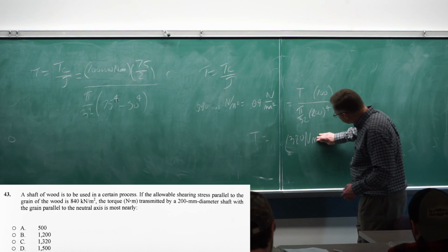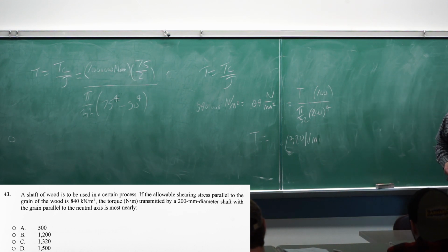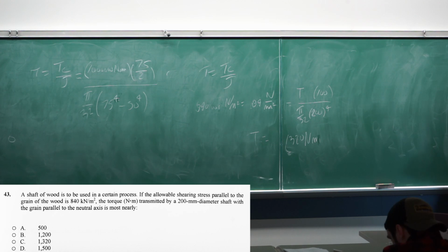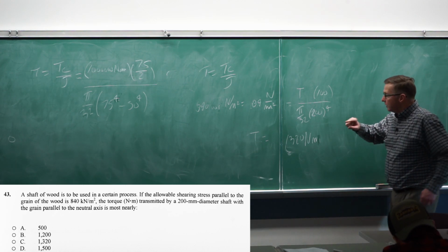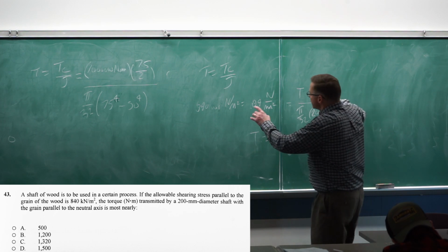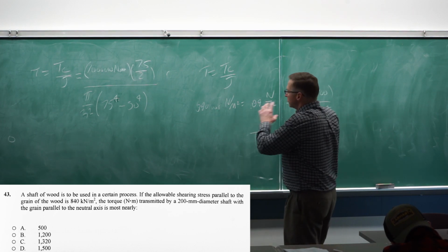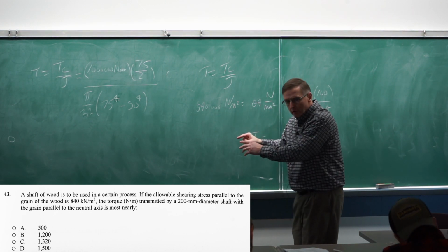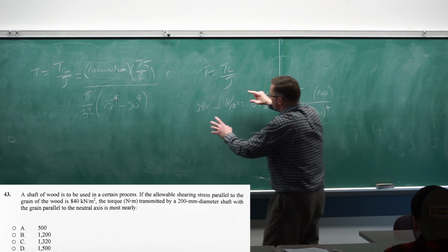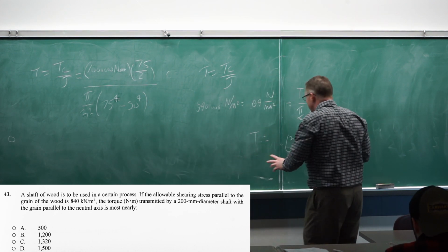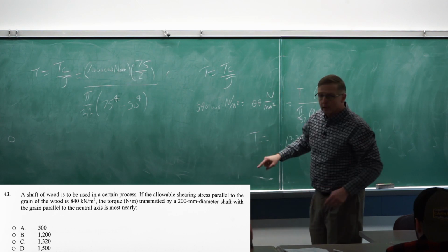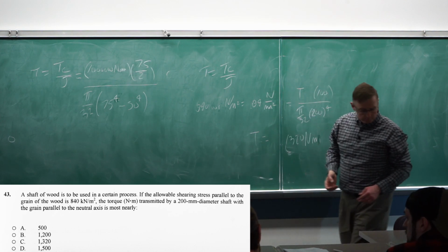Okay, I'm going to raise that then. So we okay with that one? My preference is when you're doing the calculations, take all the input in and do the calculations in newtons and millimeters, even if you have to adjust things at the beginning and at the end, so that while you know what you're doing, your calculations work out right.